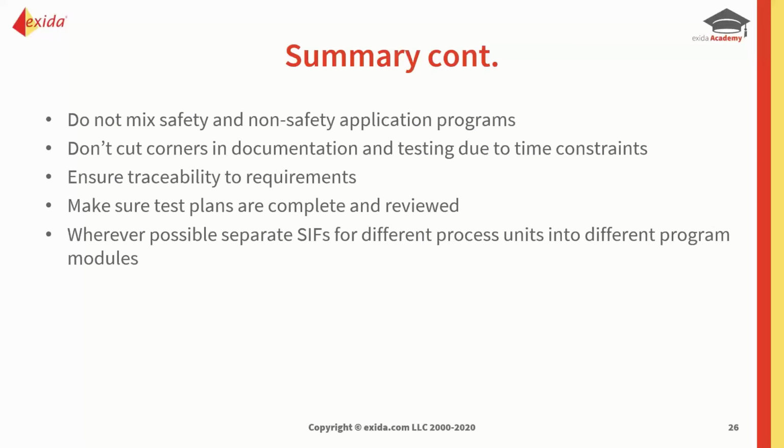And make sure that it's traceable to requirements, so that when we do our testing and get our results, we can prove that we've met requirements. So again, that comes back to keeping things as small and modular as possible. Make sure that all the test plans are complete and reviewed, and they need to be reviewed by either a person or a team that are competent to do that. And wherever possible, separate your SIFs for different process units into different modules.